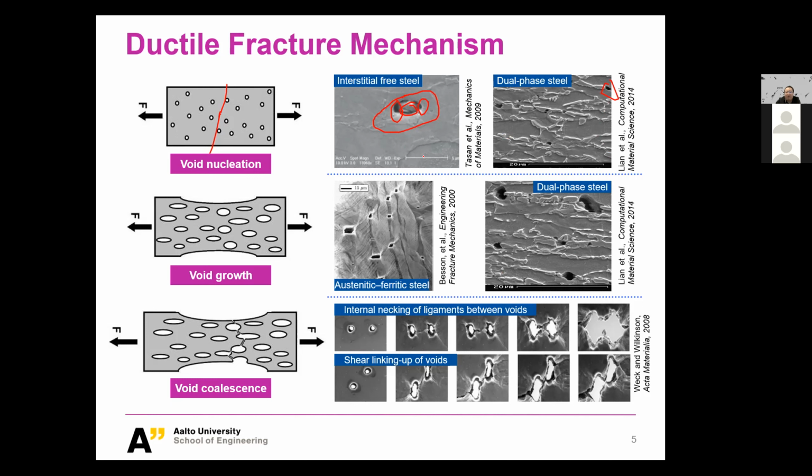So this is universal. I'm just giving you two examples. Actually, this is rather universal for any, let's say, ductile fracture or void nucleation. The difference is the hard and soft, they're always different. So you could look at different microstructure features to identify your hard and soft, but the mechanism is always like this.